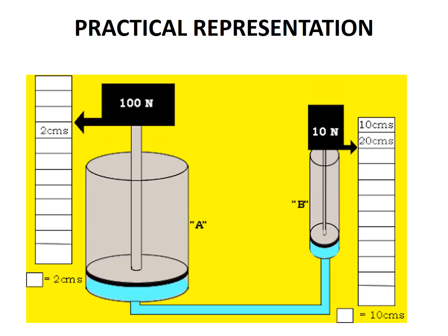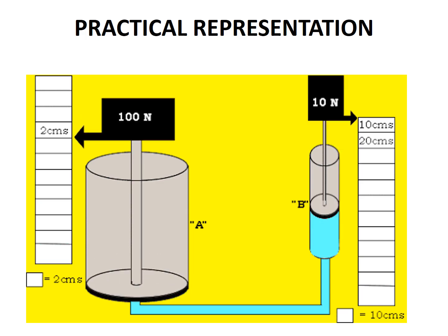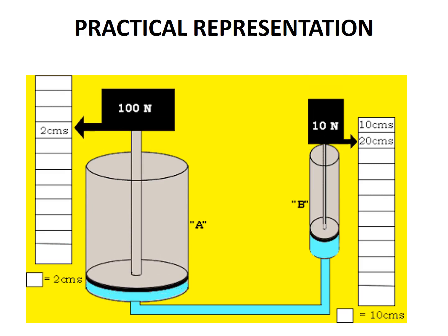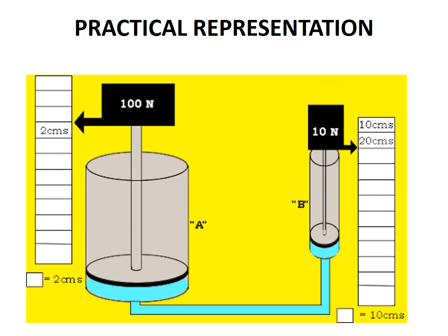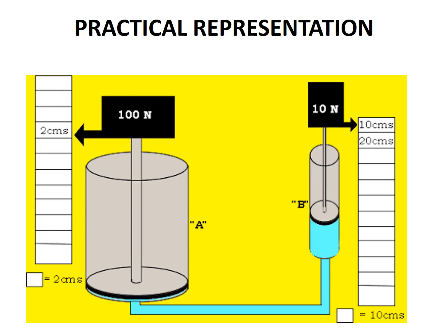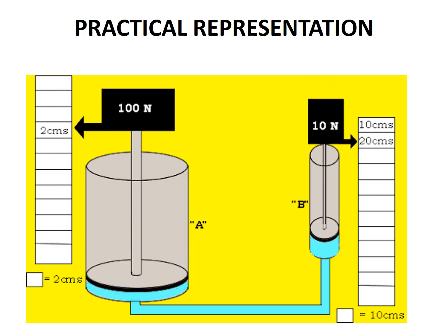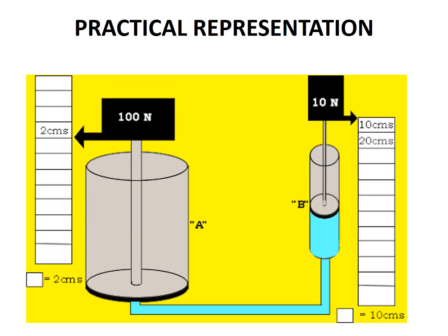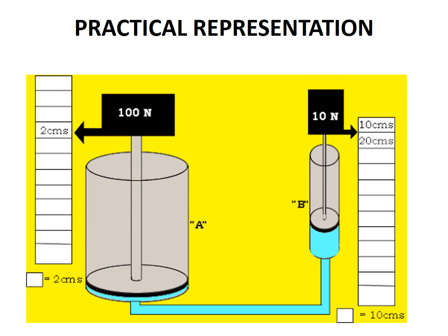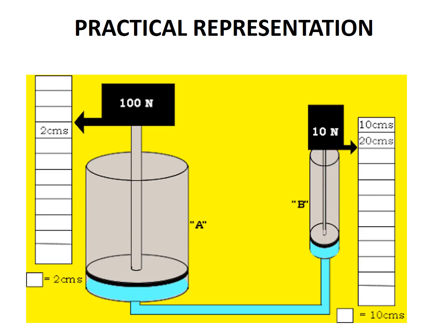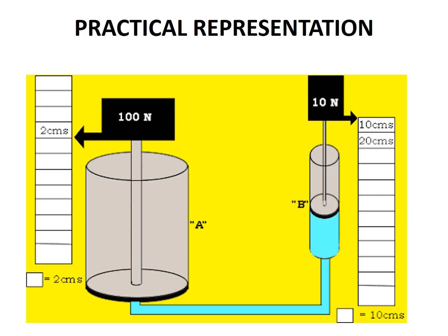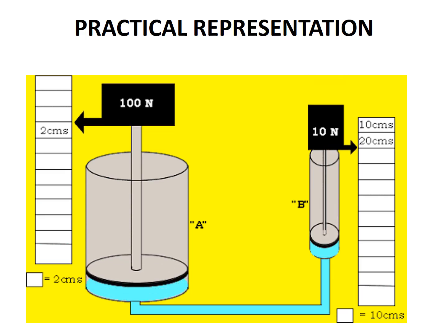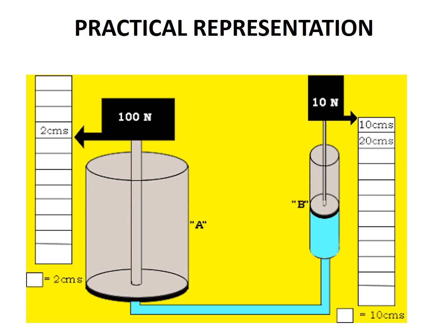But let's now look at the force applied. See, as you look into suppose the smaller cylinder as an input or a master cylinder, just going to need a little force of 10 newtons to move a force which is 10 times bigger than the input, which is 100 newtons. That is why it becomes very easy for you as an individual to be able to move a car up. That is the introduction to pneumatics and hydraulics, ladies and gentlemen.